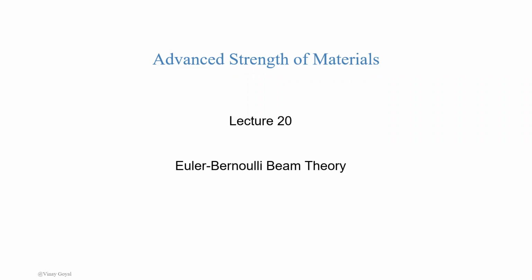Advanced strength of materials, I'll be covering Euler-Bernoulli beam theory. And what that is is a one-dimensional theory that is used to simulate structures. And these structures are slender in the cross-sectional direction compared to the length of that beam, of that structure. Those are beams. Beams are long and are longer than the cross-section in general. And that's a very good approach to simulate a lot of problems.